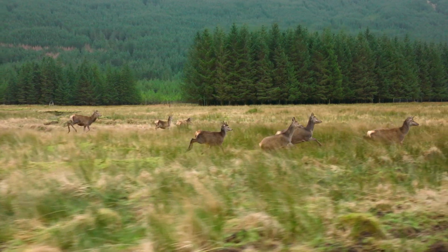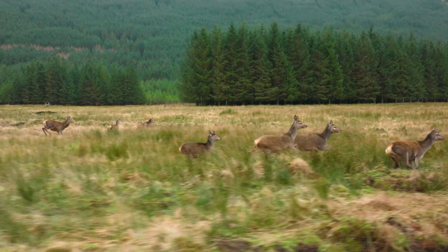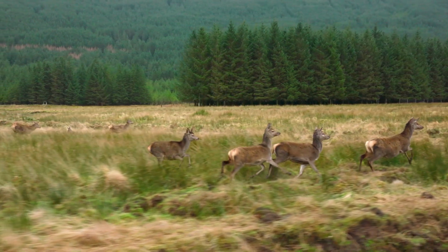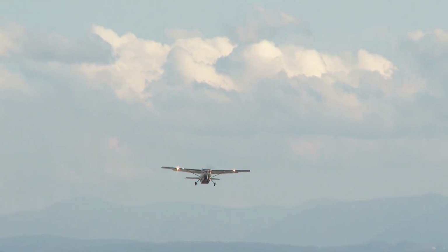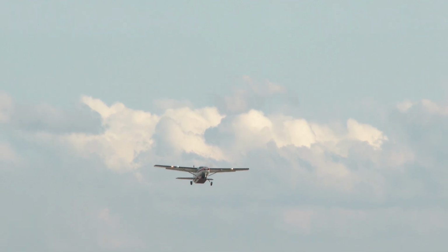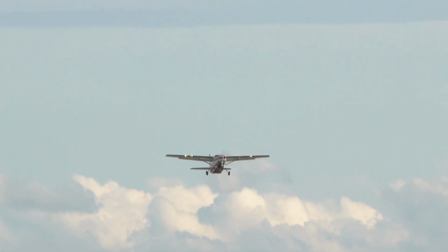If some knucklehead flung himself onto the runway, or if for any reason you decide that attempting to land would be unsafe, you can always initiate a go-around. Chapter 13 of the Airplane Flying Handbook outlines the procedure for a go-around. Advance the throttle to takeoff power and adjust pitch to arrest the sink rate. Once you have enough airspeed, you can pitch for a climb attitude and set your flaps to a climb setting.